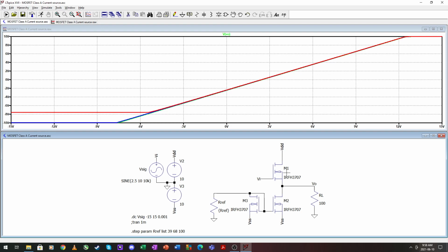But that is for milliamp outputs only, so not huge driving circuits for 100 ohm resistors or speakers or whatnot, and that's why an op-amp can't drive a loudspeaker, and you need to apply some form of stage like this. Any case, thank you for watching and see you in a next video.